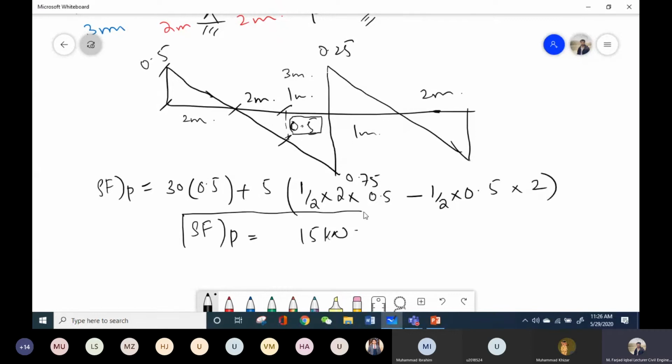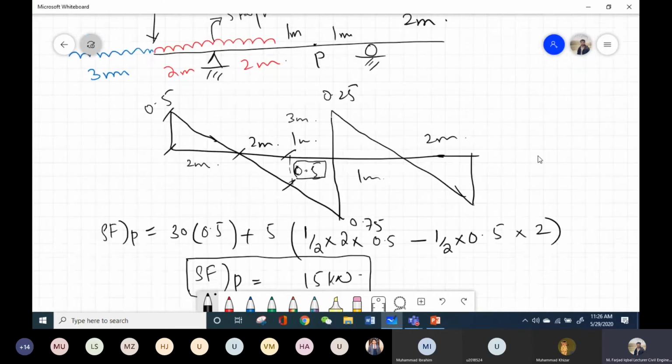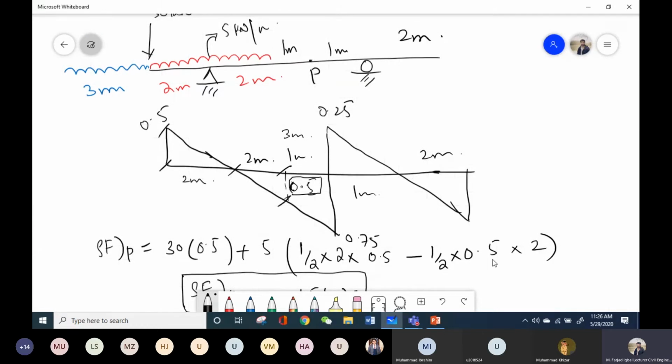But in this one, you can also see that still there is a negative component. And we can visually look at this beam, and maybe there is a case that we completely eliminate this negative component and find such a location for this live UDL that we will have only positive triangles. So this is only possible in one case that I placed.